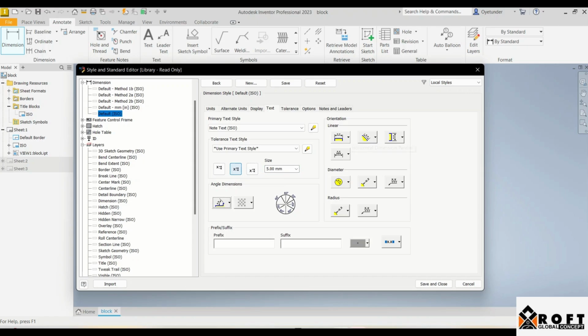And also the orientation of my dimension, we have different options. We have one where your dimension will be on the line, one that will be in the line, where it will cause a break while your dimension sits in it, and we also have one which is going to sit on the line.